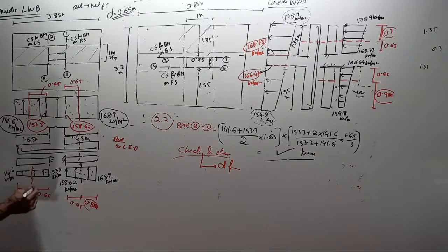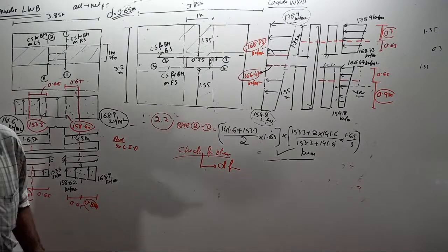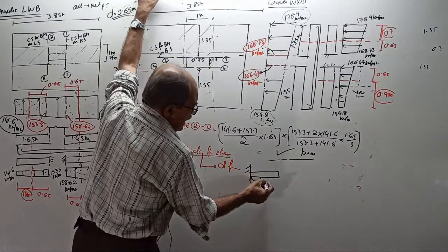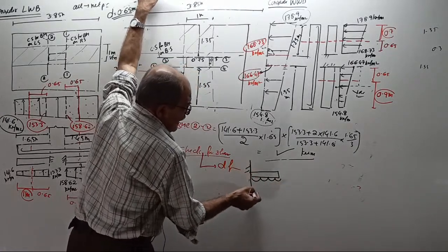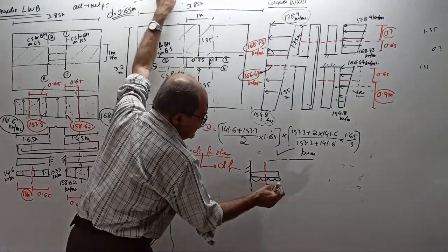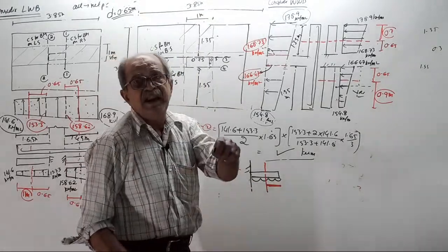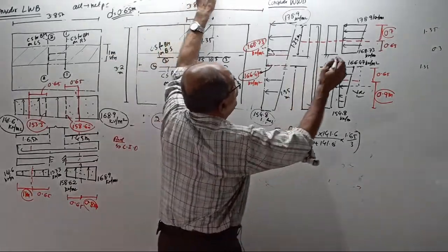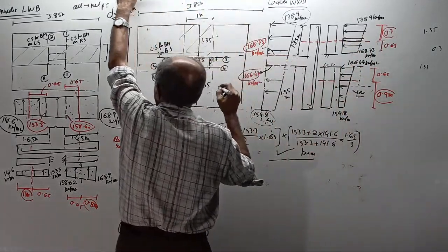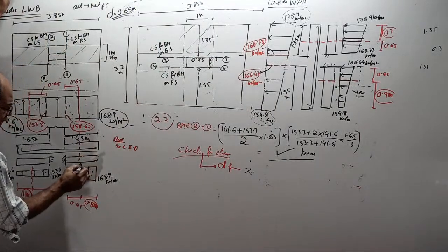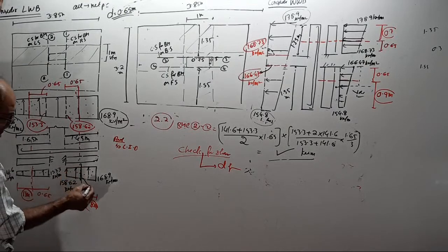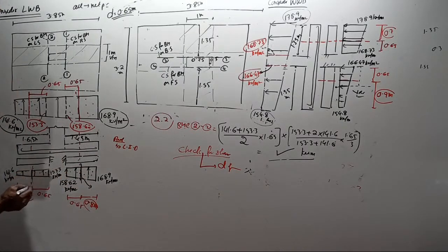1 meter. Okay. Now, remember, I told you earlier, in case of a cantilever, if UDL is there, when you want maximum bending moment, take the full load. But when you want shear force here, only this much load. You should look from the free end side. Therefore, now you need to know what is this intensity, what is this pressure. You need all this pressure. By interpolation, you have to get this pressure also.